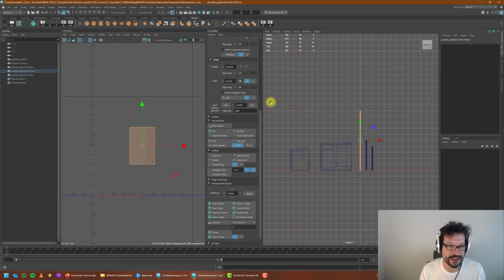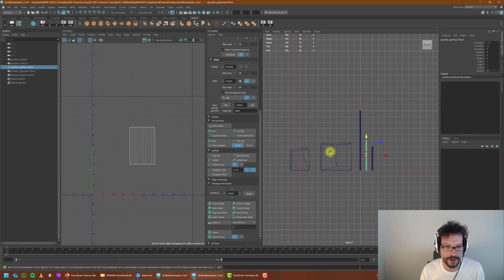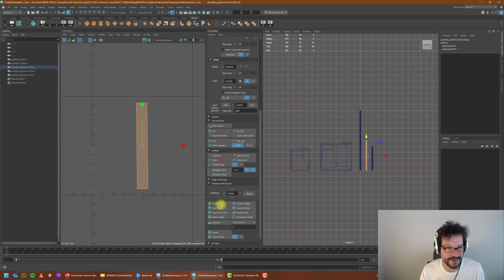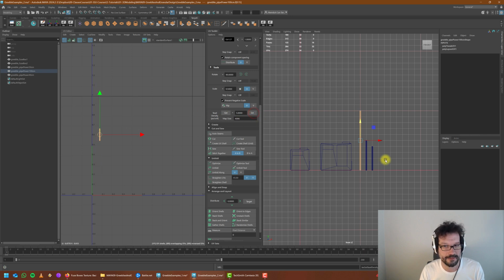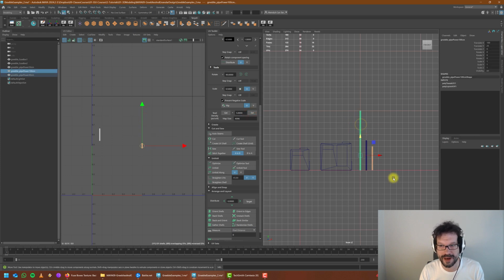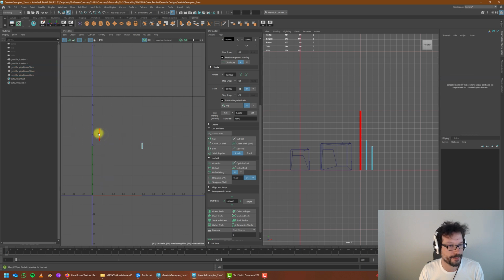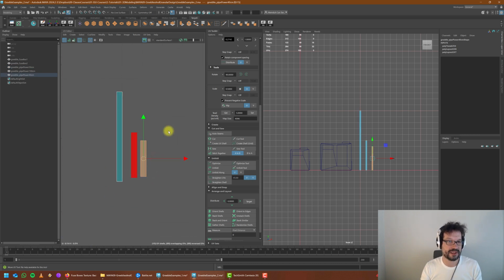Like, let's go to their UV shells, let's grab everything. First of all, let's unfold them, okay, and then orient them and then lay them out. Oh, you have to do them separately, unfortunately. Okay, and unfold, orient. And if you do this from the beginning, it's going to be easier, obviously. Let's once again set the size. Okay, good. Now grab all of them and put them side by side. We can arrange them later.